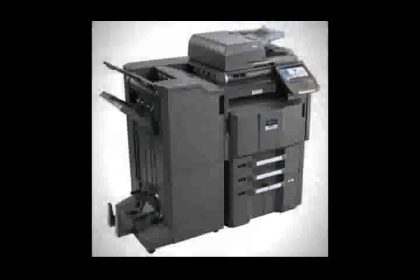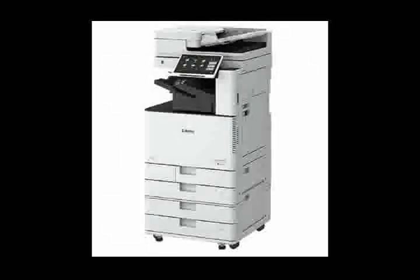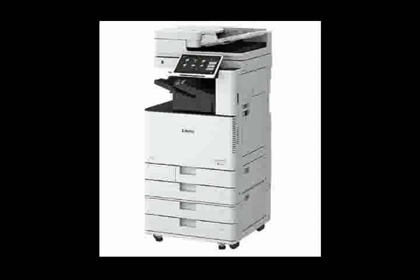Other refinements of copier systems include the use of electronics and advanced optical lens systems. The size of the copy can be enlarged or reduced by adjusting the distance between the optical lens and the image. Lightening or darkening the copy is achieved by changing the intensity of the light beam. Electronic counters are used to indicate the number of copies needed. Diagnostic circuits can also be used to indicate conditions such as paper jams, low toner, or an empty paper tray.